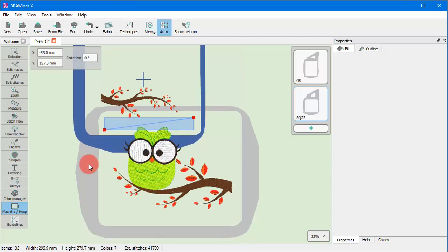Now we need to make a few adjustments. The intersected area, which is highlighted with a blue transparent color, includes a diagonal line that specifies which objects will be cut if they cannot fit entirely in one of the hoops. In our case, the upper branch fits entirely into the second hoop, so we'd better move this line up.